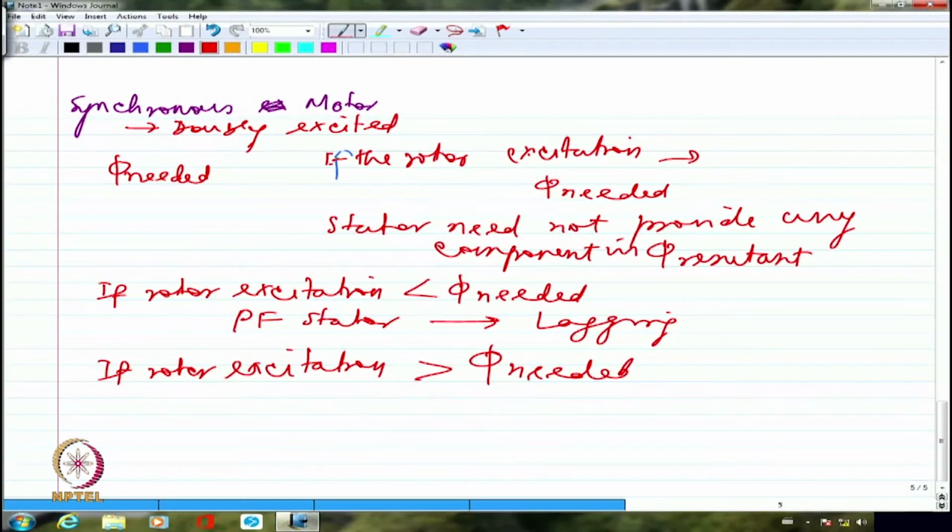Please understand, unless I have a certain amount of flux, I will not be able to produce the torque, because in the alignment process also, the magnitude is very much involved. It's not only a north pole and south pole per se. It has to have certain magnitude. Unless it has sufficient magnitude, I'm not going to be able to pull the rotor. Right? The rotor has some weight. It's not weightless. So I will definitely need a particular strength of the flux, and a particular strength of the current from the stator side. All that put together only will develop a torque.